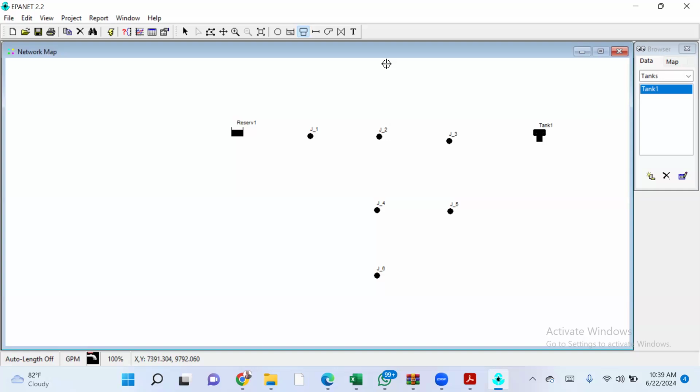The next is the last paragraph, paragraph 3, drawing the network links. After adding this one, your mouse will be showing action. Please go and click the black arrow again. You must be fond of clicking this black arrow to deselect. Now, we'll click on pipe. Watch me. I will not click from reservoir to 1, though. I'll start from number 1.